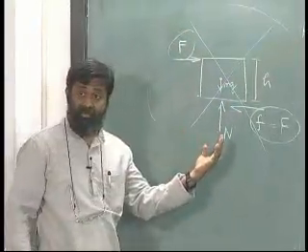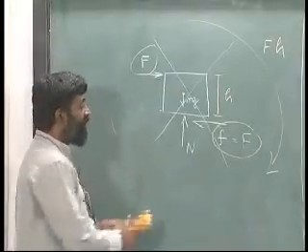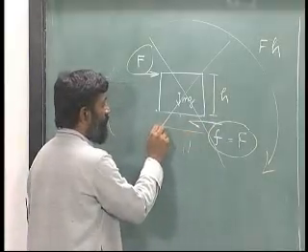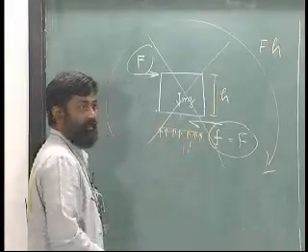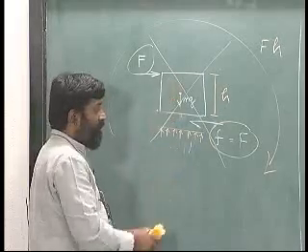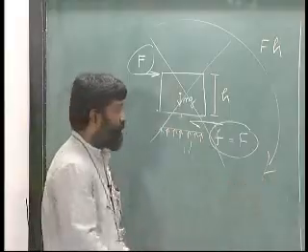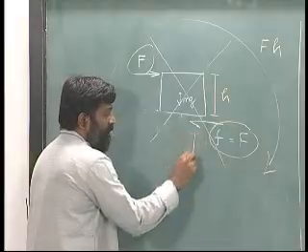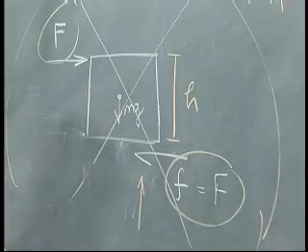Where is the resistance to that couple? The resistance is offered by a variation. For example, if I draw the normal reaction to be uniform like this, then its resultant is along mg. Actually, since I have to offset this couple in the static case, the normal reaction N will shift like this, so that this will form an opposite couple.